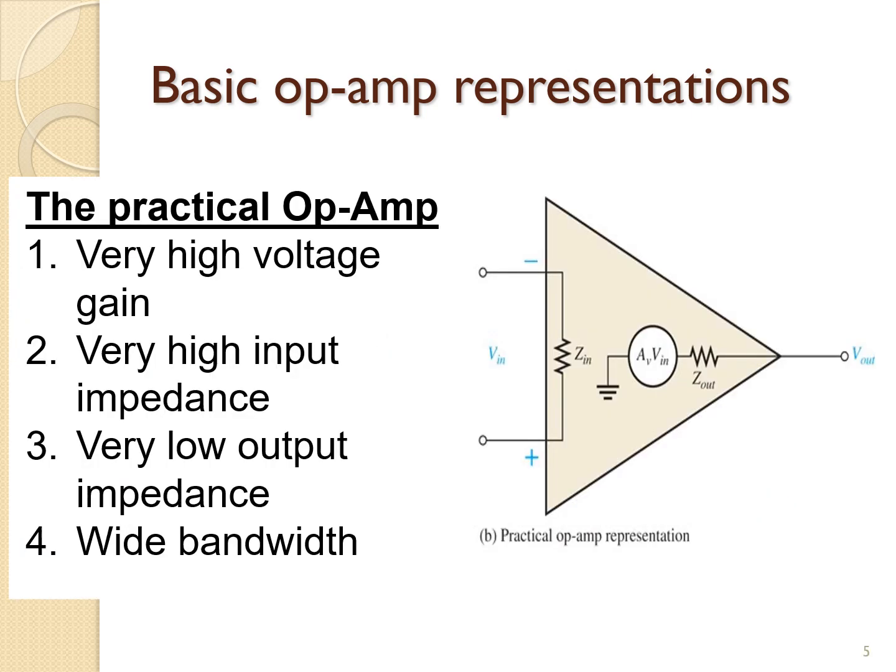Although integrated circuit OpAmps approach parameter values that can be treated as ideal in many cases, the ideal device can never be made. Any device has limitations, and the IC OpAmp is no exception. Peak-to-peak output voltage, for example, is usually limited to slightly less than the two supply voltages.